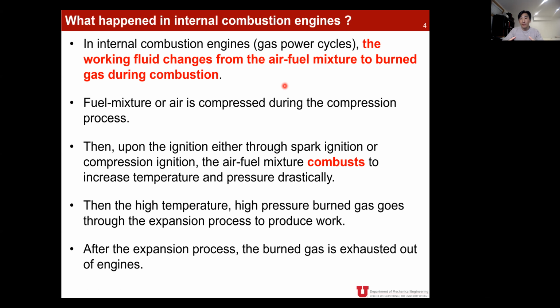And what happens after this combustion process or chemical reaction process, air and fuel are chemically reacted to produce certain burned gas mixtures, like water vapor, carbon dioxide, also nitrogen, and so on. So during the overall process, your working fluid composition changes from air-fuel mixture to different burned gas mixtures.